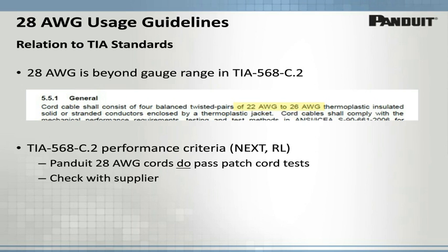Thank you. Question asks, what happens if the standard Cat6a patch cords are utilized at the workstation? Cat6a cabling is used in the horizontal for 90 meters maximum, and then the smaller diameter, the 28 gauge Cat6a patch cords are used only in the telecommunications room.